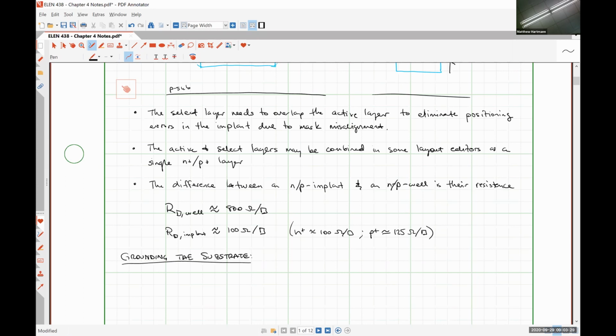Now that is important due to the body effects in transistors that we'll talk about in a couple of days and all that kind of stuff. But how it's done is also important, because the substrate isn't just inherently at a potential of 0 volts. We actually have to connect it to an external ground to the chip to cause that to happen.